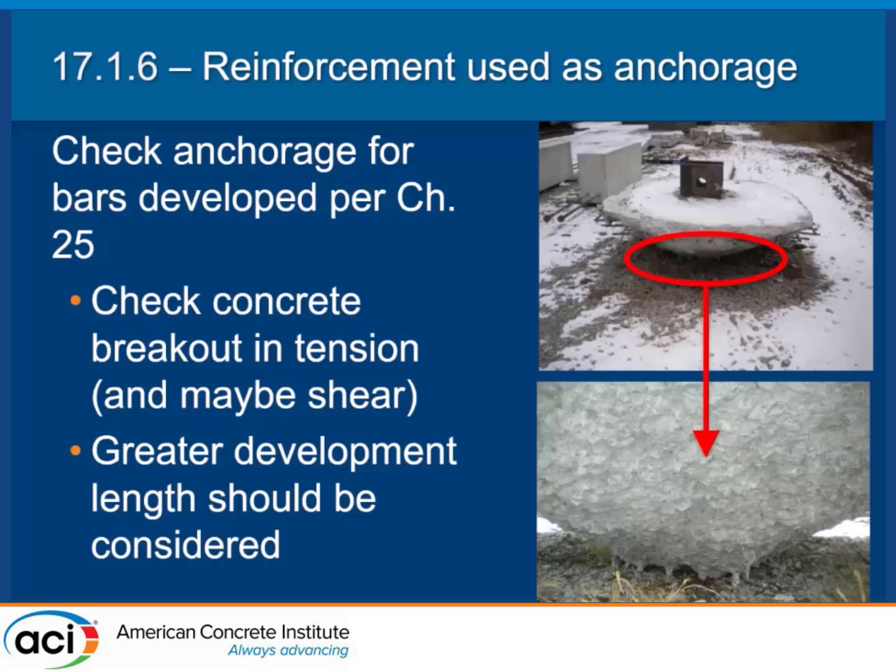What I want to drive home on that is think of that you're in the top of a wall. We've got a typical outside wall or something. You put a couple number 4s in the top for nosing, and you put an anchor up there, and they go, well, that should be doing something for me. It does nothing for you in tension. Absolutely nothing. So this drives home the point that if you're going to provide anchorage or supplementary reinforcement, it has to be opposite the direction of the load to be of any effect, to help transfer that load into a bigger hunk of concrete.